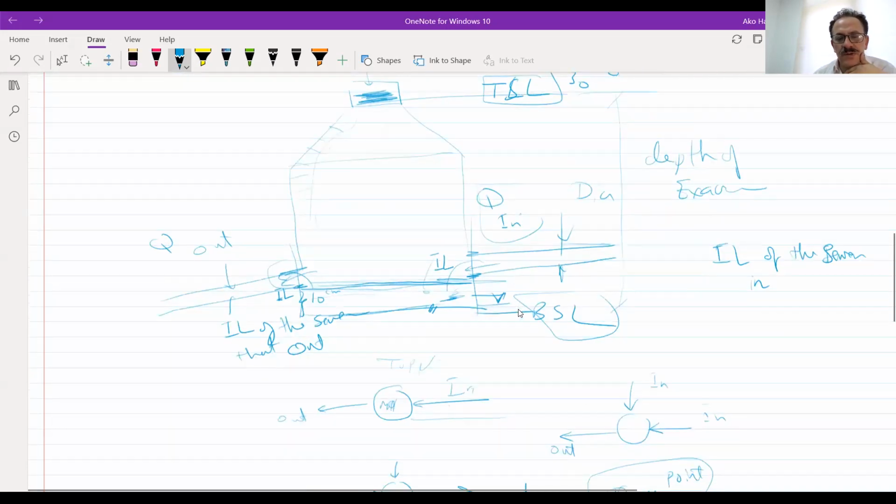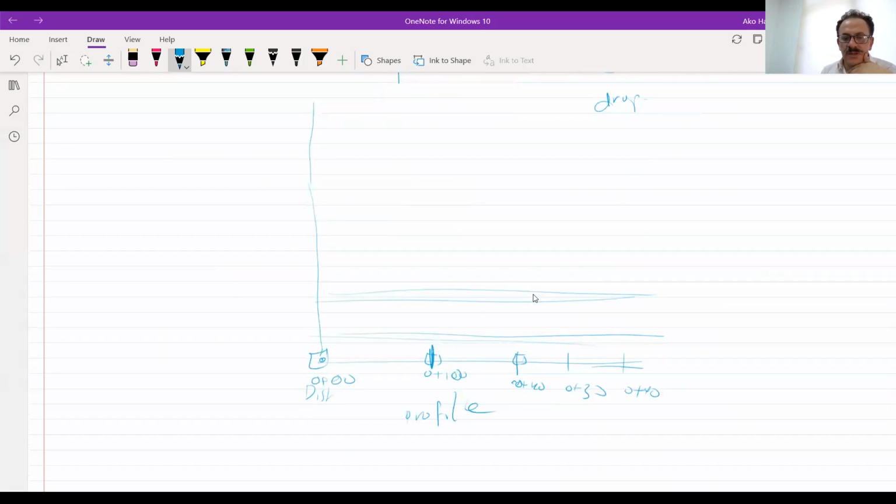We have another manhole, so we have to mention that one in the profile. I will say there is manhole number 2, and manhole number 1. Okay, and you have to mention the ground level, the manhole cover surface level, and the bottom surface level, and here it's the same. So you have to mention 3 numbers and put them at the level that is mentioned.